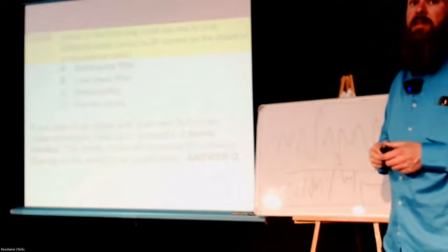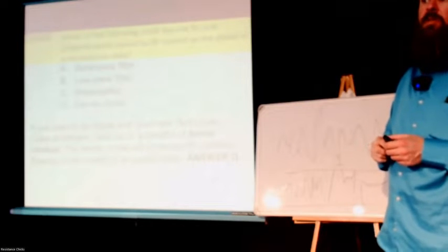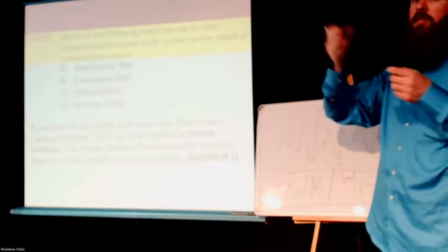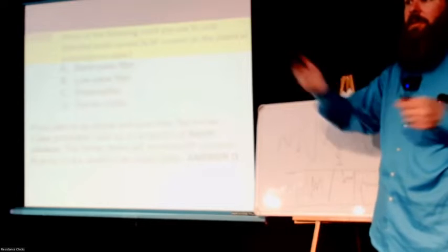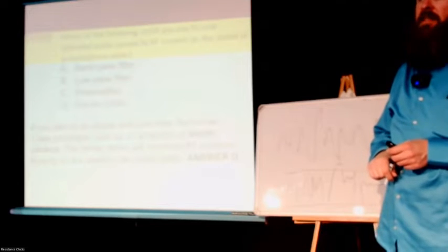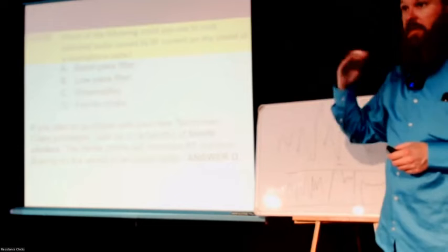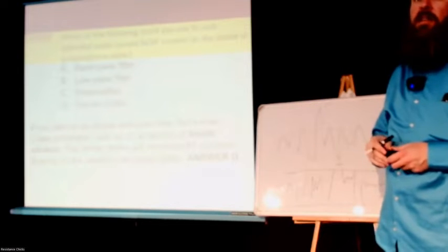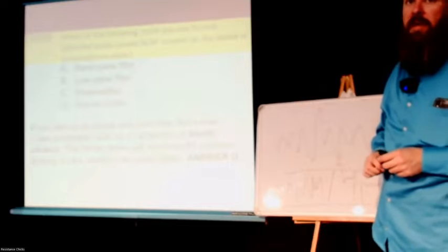Yep. Right there on the end of that cable. That is a ferrite choke. And what that does is it stops signals from coming onto the outside of the cable from the air and traveling into the device. So that's what keeps their microphone from getting buzzes. And if that wasn't there, there would very likely be a constant buzz, especially from fluorescent lights above. That's what eliminates that.